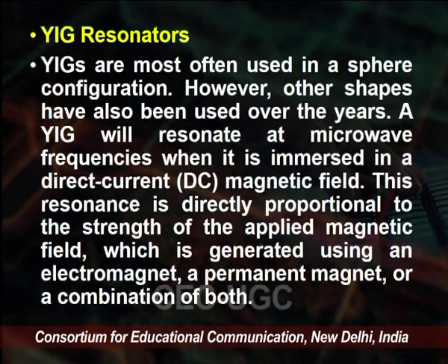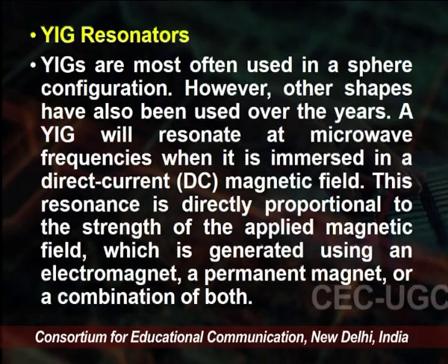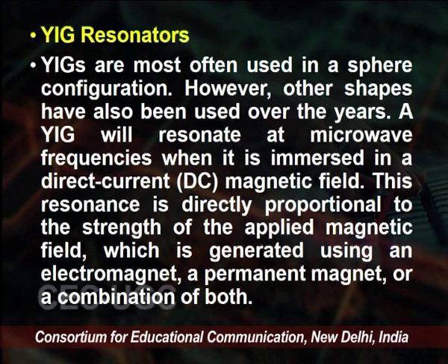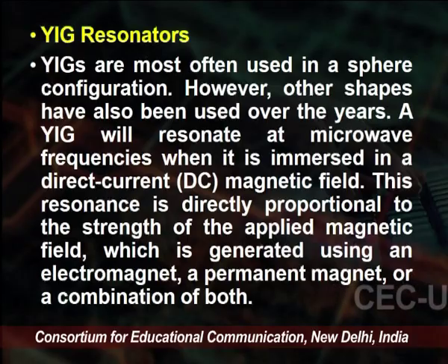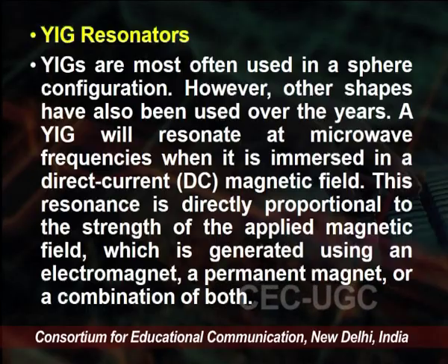So, YIG will resonate at microwave frequency when it is immersed in a direct current magnetic field. This resonance is directly proportional to the strength of the applied magnetic field, which is generated using an electromagnet, a permanent magnet or a combination of both.